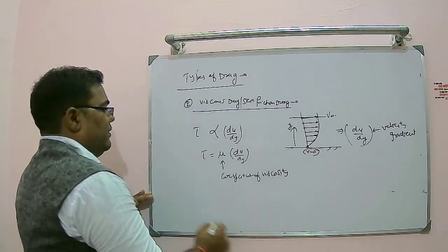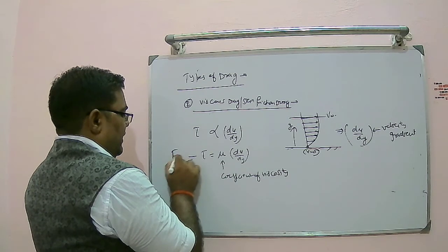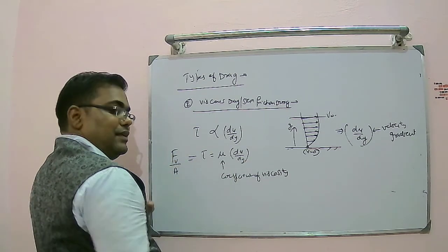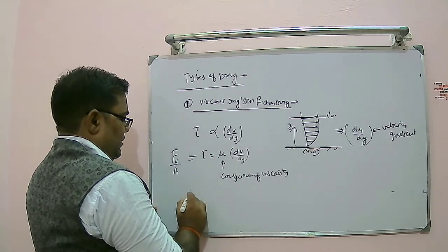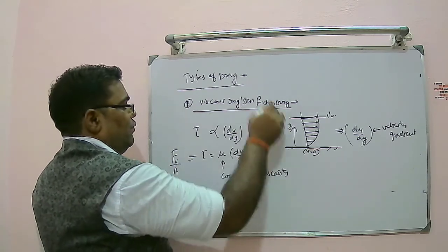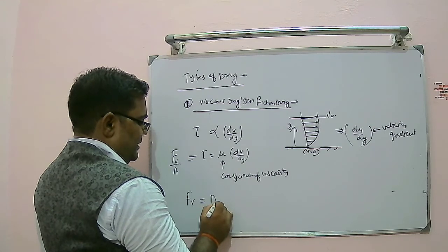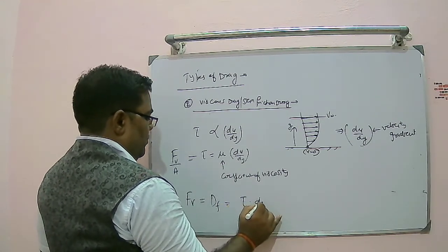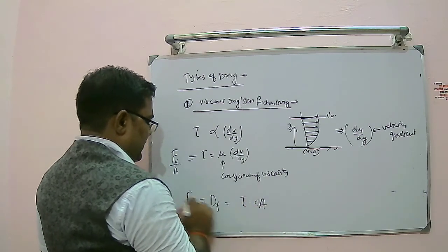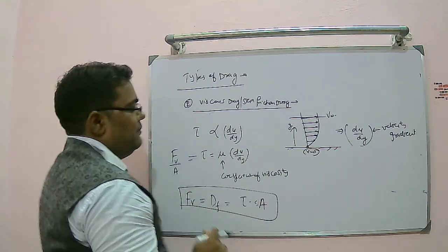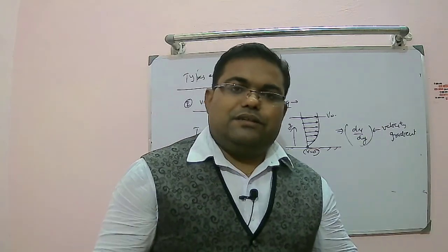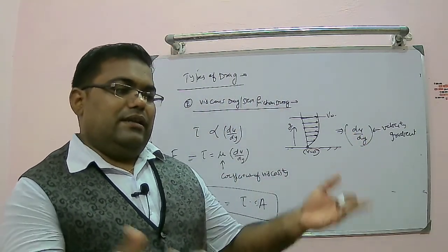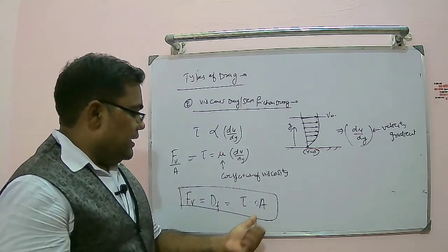So when you are talking about drag force, this tau is nothing but F viscous divided by area. Alright, so I can say frictional or skin friction force or drag, sometimes we say dF is also correct for this. This is nothing but tau into area. And which area? Basically this area is surface area. Basically it will be taking surface area of the plate, pi dl in the case of circular cylinder, or length and width that you consider. So the area is surface area.